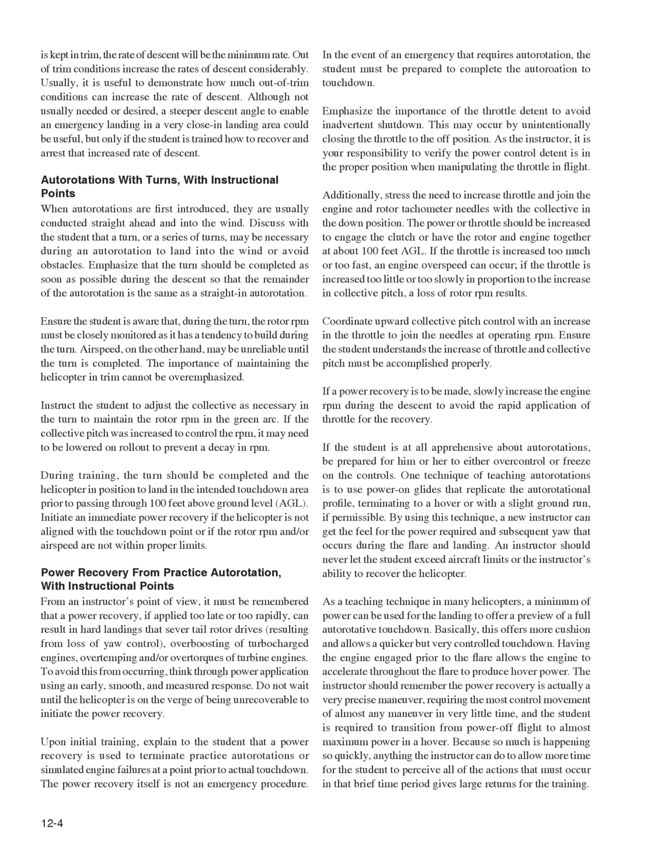Instruct the student to adjust the collective as necessary in the turn to maintain the rotor RPM in the green arc. If the collective pitch was increased to control the RPM, it may need to be lowered on rollout to prevent a decay in RPM.